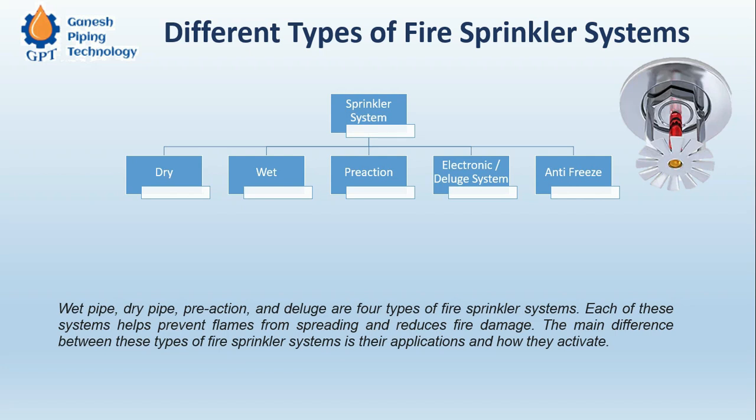When the bulb melts, the pressurized water contained in the header will start spraying over the area where there is a temperature rise, and this is how it can extinguish the fire. And in case it doesn't extinguish it, it slows down the spread of fire, as the temperature of the surroundings will decrease because of the continuous spray of water.